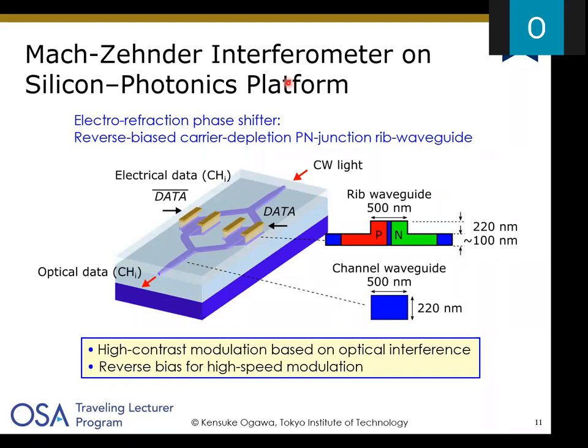Yeah, that's different. The photonic band gap is defined with the array of the dielectric materials. If you change the pitch of the array of the dielectric medium, you can change the photonic band gap. But there is no change in the electrical band gap. The electrical band gap is determined by the crystalline properties of the material.